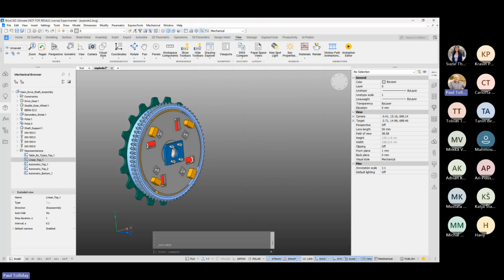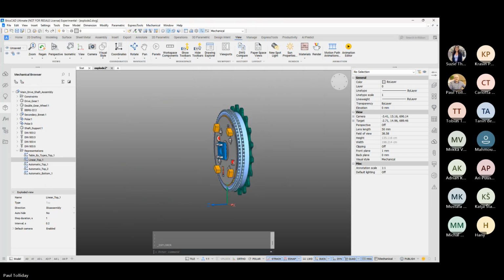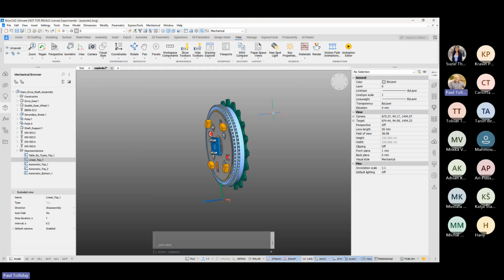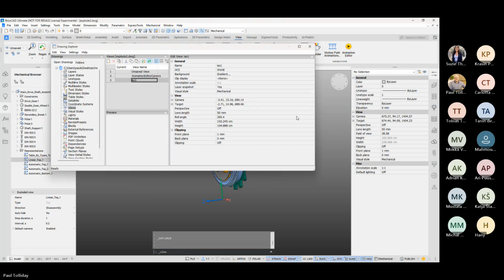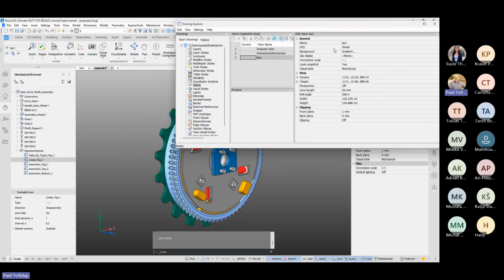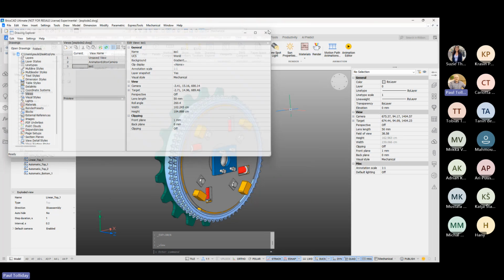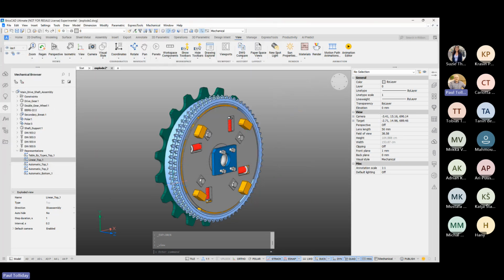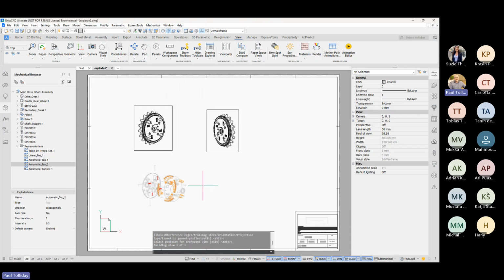So now, if I move this around, and I go back to my view, I can select ISO 1, and you'll see that moves into the right area. So it's that actual view. So that's now a view that I can replicate. So again, with any of these views here, I can just simply right click, go to Automatic 2D, generate view, and it'll be the view they've got on the screen that is now repeatable, even if I want to move the component around. And that's going to come in very useful later on as well.